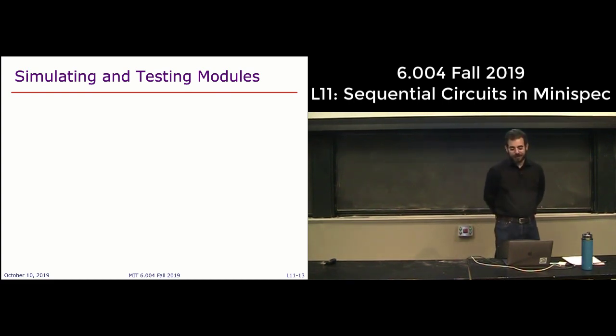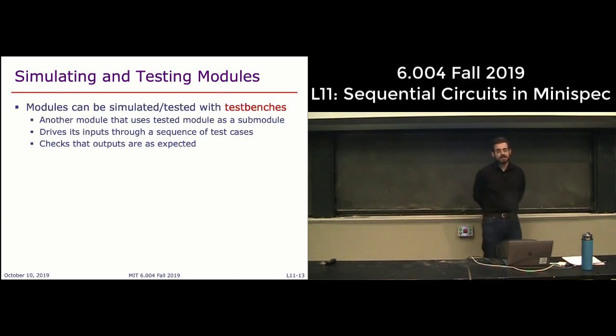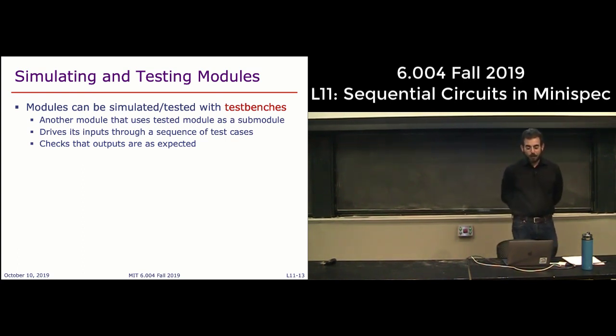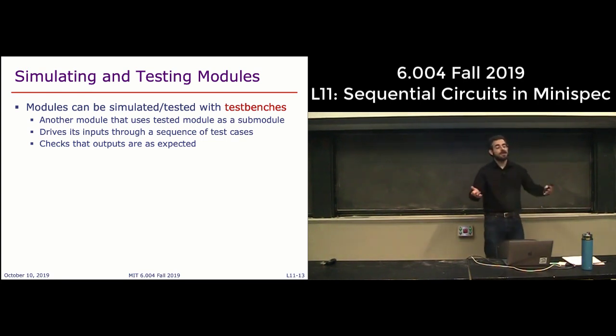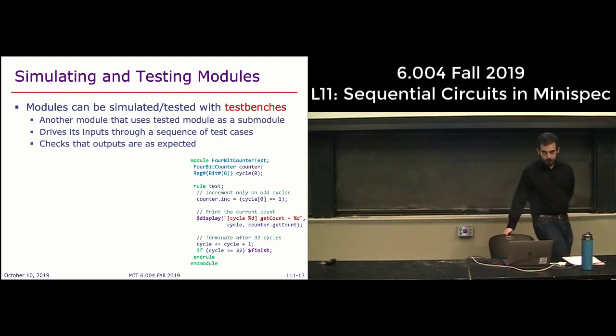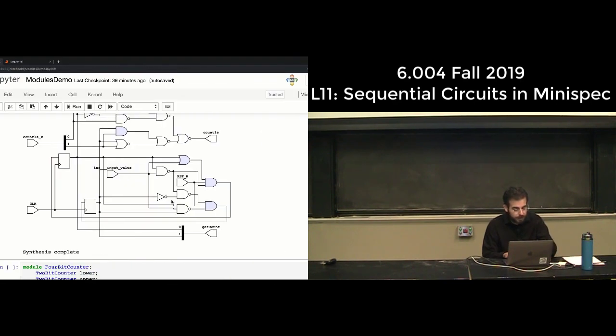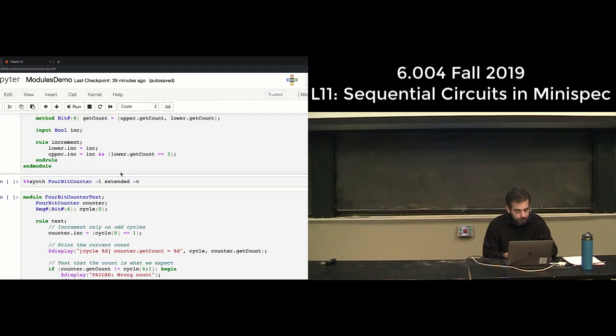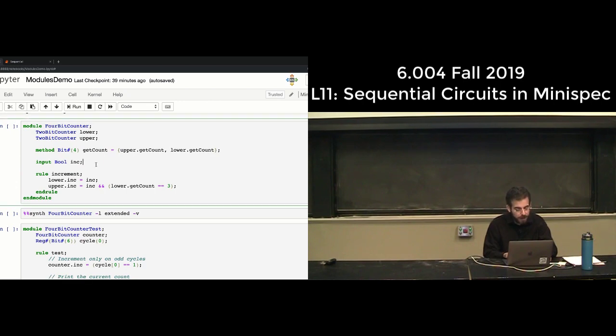So you need to get into the habit of writing your own testing modules, and the way that we do this is by writing what we call test benches. A test bench is another module, just more sequential logic, that uses the module we want to test as a submodule, sets its inputs, checks its outputs. That's it. Let me actually just show you a quick demo of this. But to do this, we are going to need a little bit of help from the language in the form of what we call